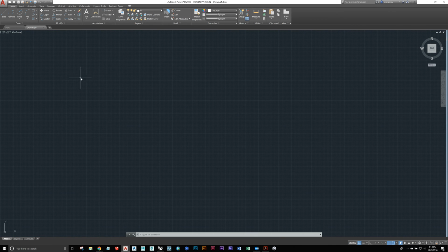So what we'll cover now is how to create a few basic types of geometry. First, we can click on the line, and you can draw single lines. You can see that as I move this, the length of the line is displayed. And then right on the cursor, you can see that the angle of the line from the starting point is displayed as well. And I can just move quickly to draw something. When I'm done, hit enter. However, these all display as separate lines. They do have control points you can use to manipulate the lines.